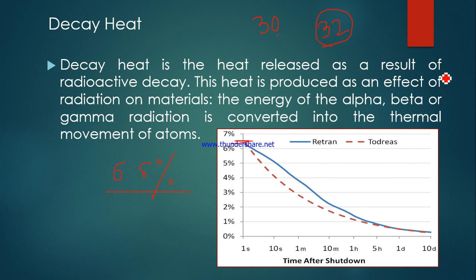So what I mean to say is, these decay heat exchangers should be naturally cooled. The flow should be on the tube and shell side. On the shell side it will be air, so it works due to thermal siphoning. Cool air enters from the bottom, and once it is heated up, the density of the air reduces and it gradually goes up, and this will establish the flow in the shell side.